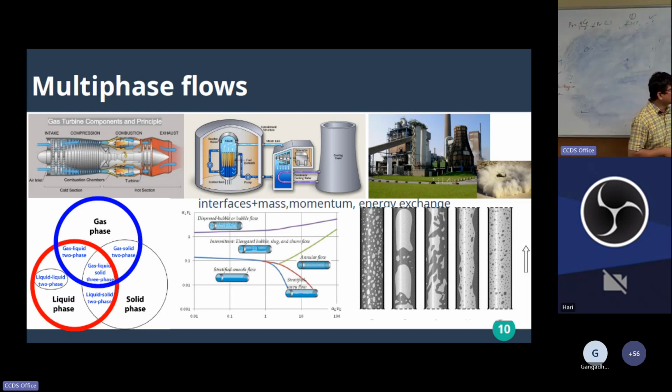There will always be something like dispersion, based on how much gas flow rate is passing and how much liquid flow rate is passing. This is what we call superficial velocities within a given cross section. If you are taking entrance conditions, how much gas is interacting with liquid. Based on that, you will have completely different kinds of problems, and different solvers exist.